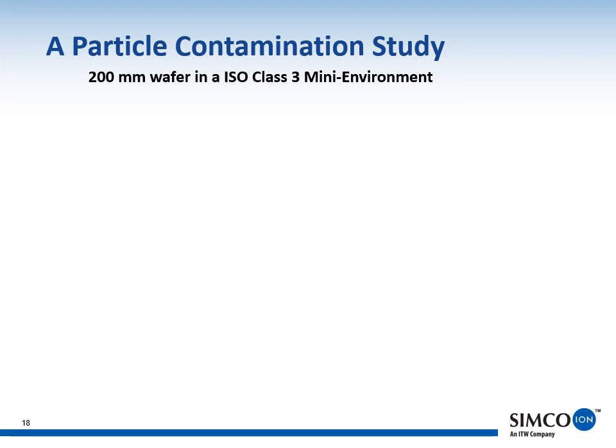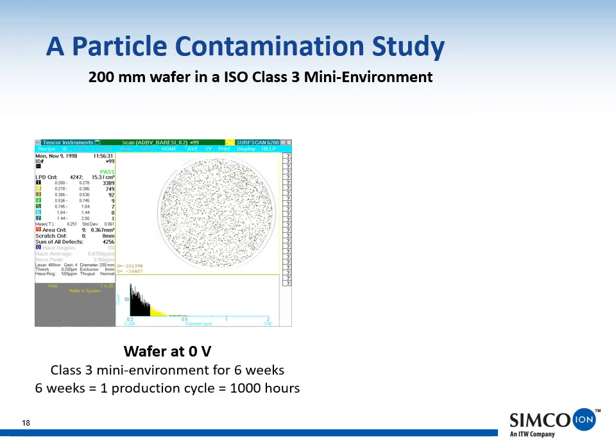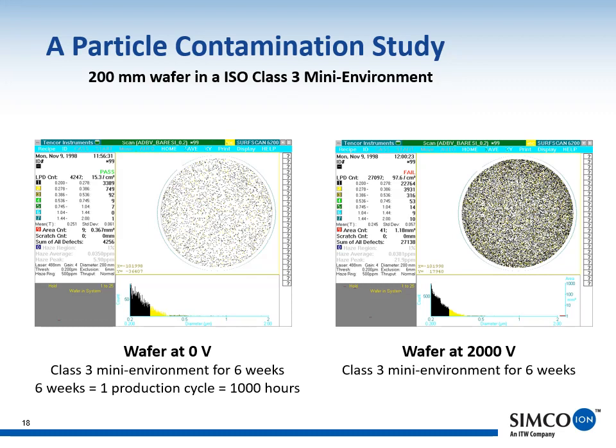This is another study that was done where a wafer was held at 0 volts for 6 weeks in a very clean environment, ISO 3. Then another wafer was held in the same environment at 2,000 volts. In this case, the wafer that was charged attracted over 23,000 particles more than the uncharged wafer.